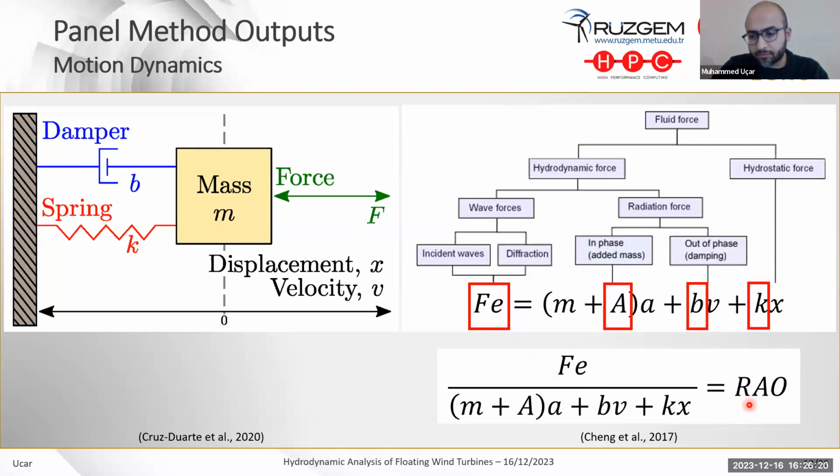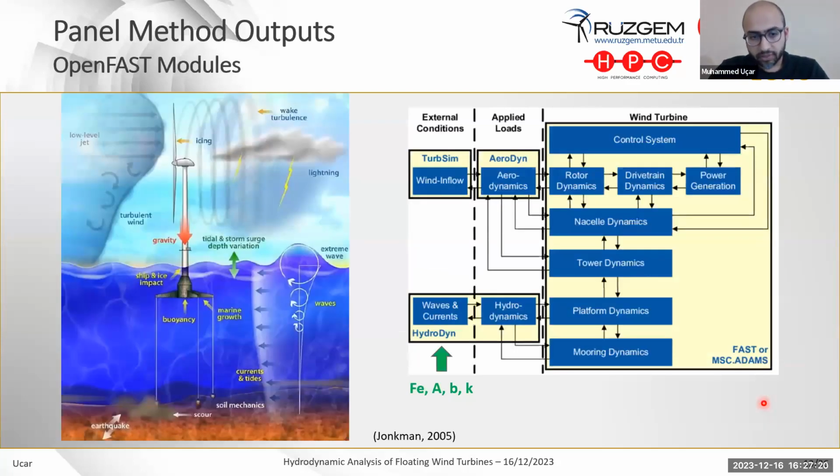Let's consider a structure exposed to wave effects. If the waves are very small with small periods, then the structure will not be excited. On the other hand, if the structure is facing, let's say, tidal waves, then we will not feel it because the waterway will pass through under the structure. So we need to decrease this response amplitude operator. That's a good point to start the optimization of this hydrodynamic analysis for a floating platform. So let's turn back to the general overview.